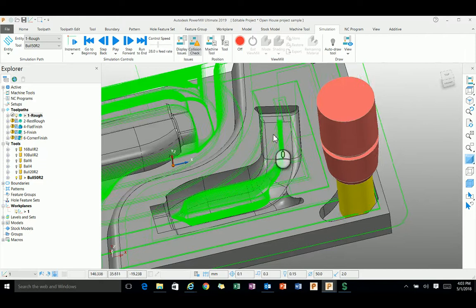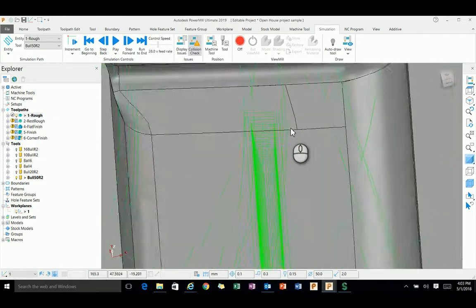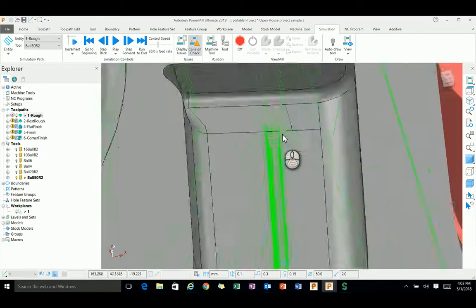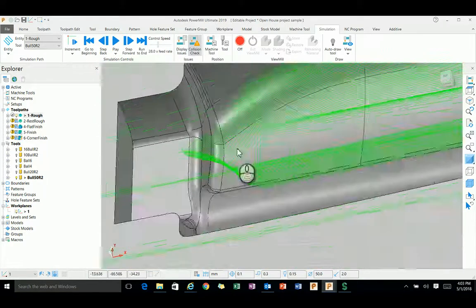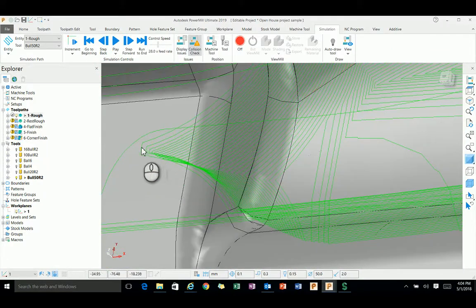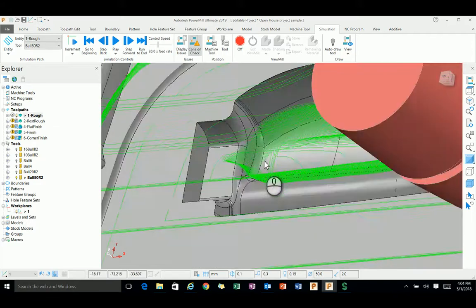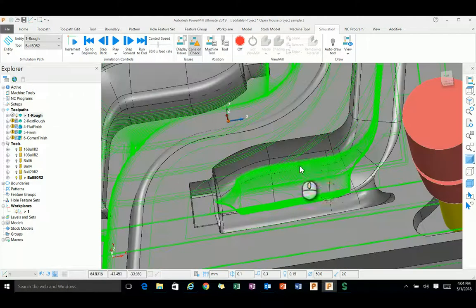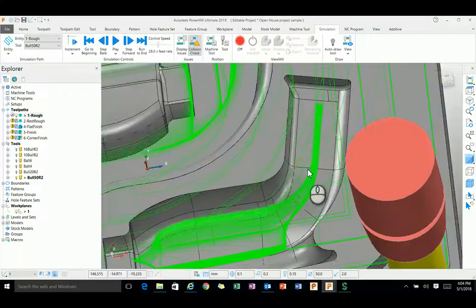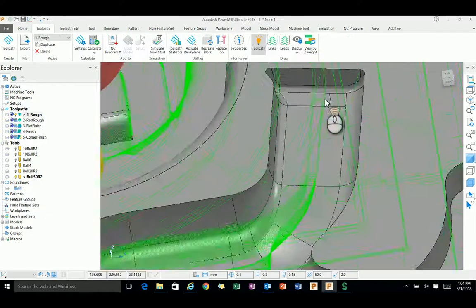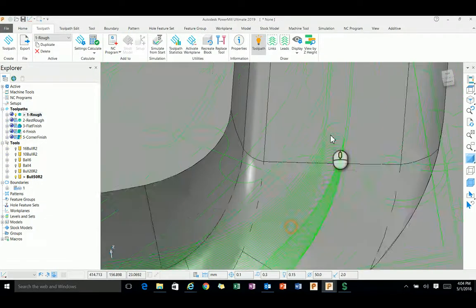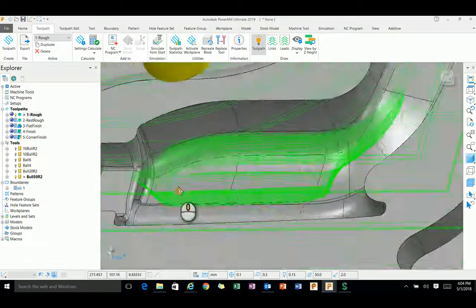And the second option that I want to highlight here is the sharp corners. Wherever there is corner area machining, you can see there are a lot of sharp movements in the generic PowerMill roughing toolpath, but our toolpath is more radial forms. It has created all the corners as radial fashions.